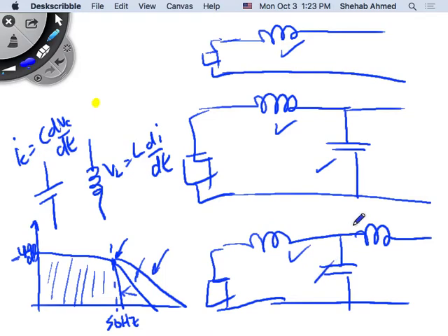That's if you're using a passive filter. If you use an op-amp filter, of course, it's a little bit different, but still very similar, because you still have these reactive elements, L's and C's around the op-amp, so it will also be defined by that. But for passive filters, this is defined by how many components you have. So you'd never use an op-amp, because then you have to pass all the power through it, and op-amps are typically low power electronics, right? So you don't want to use this.